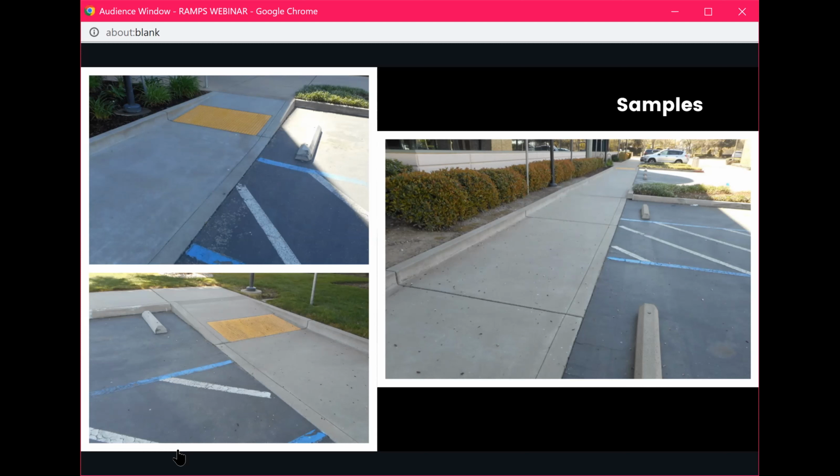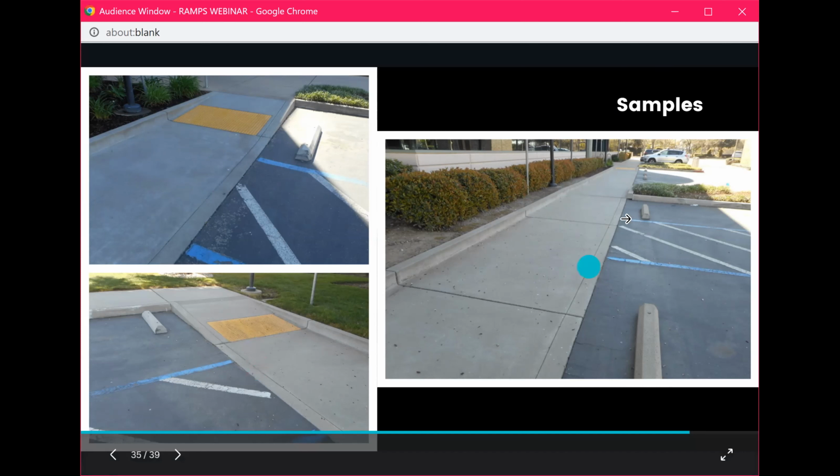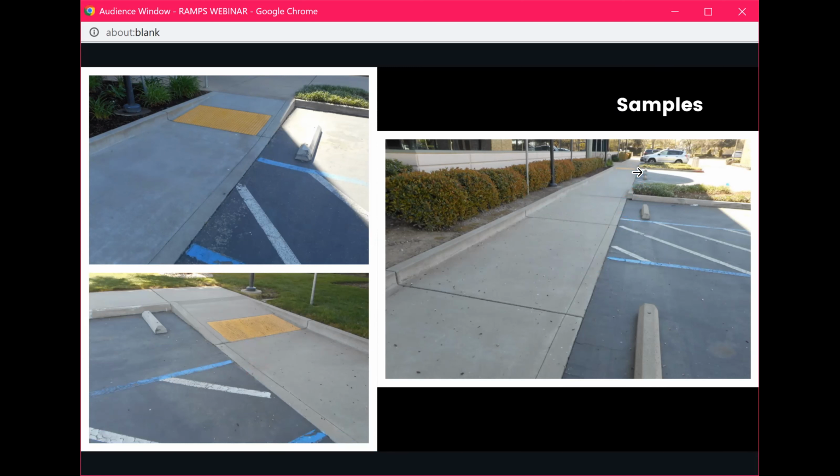This is where we would not have detectable warnings, right? Right, I guess that was my question, because I know Louis mentioned something earlier, that this is really not acceptable, and you still need to have detectable warnings in the whole strip, maybe like 14 feet. Right, so if this is a path shared by both accessible people and able-bodied people, the general public passing through, then you have to have that strip of detectables all along the run here.